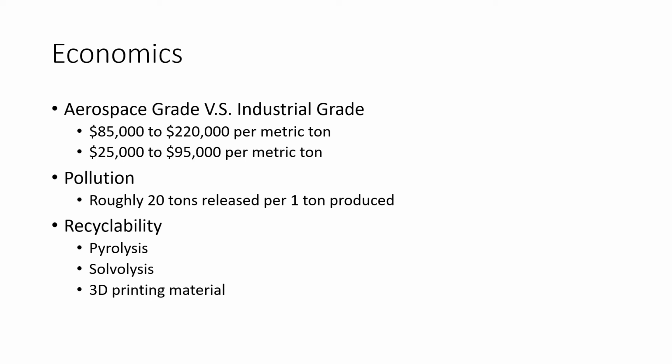This uses a solvent to dissolve the resin off the carbon fiber. They take these fibers and turn them into a denser material to be used for different applications. Once the fibers are densified, the carbon can now be used as a filament in 3D printing and injection molding. Although there is a way to recycle carbon fiber, roughly 30% of the material that is recycled goes to waste during these processes.